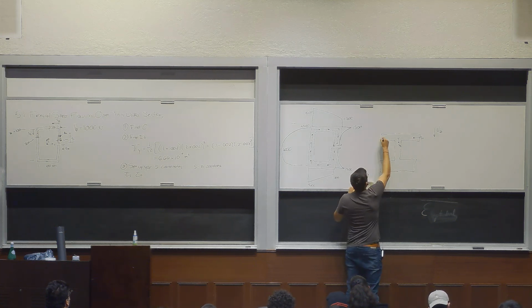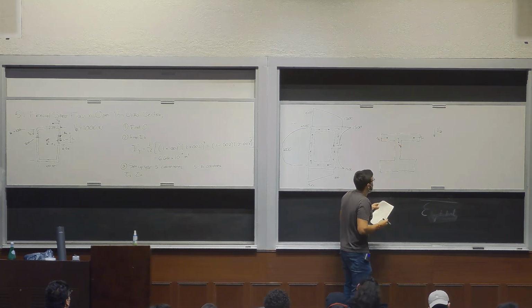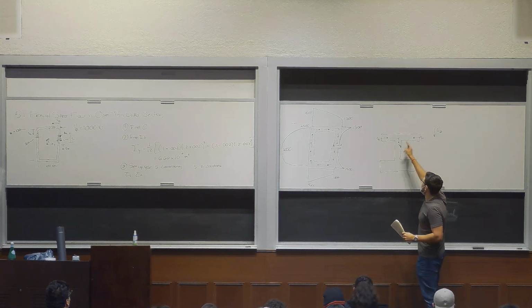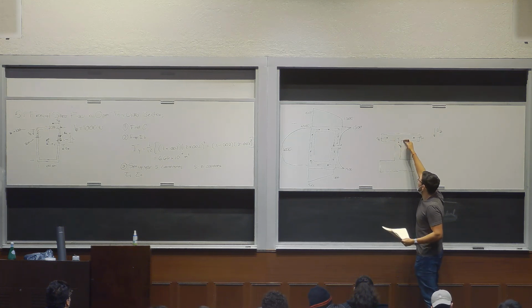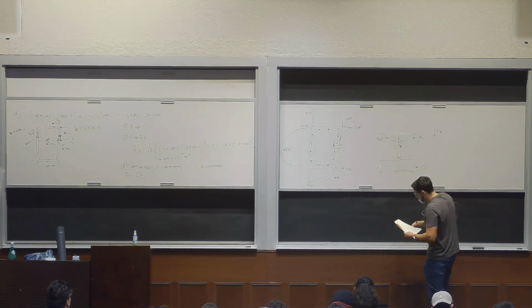So you also have to have a starting section here. So let's call this S2 and this S3. So the way you would do it is solve for the shear flow from here to here, and from here to here, using this other coordinate system. Then add those two, the big Q's, and then go for 3, okay? And then you can do the same thing down here, so S4, S5, S6, whatever.